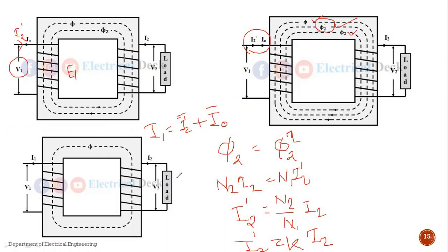And when the transformer is on no load condition, the current taken from the supply, that is I0, is again the vector sum of two components, that means the magnetizing component and the working component. The final conclusion is that the transformer operation remains the same whether it is operating on no load condition or on load condition. We have already concluded this in the previous lecture. Today I just had an overlook on that. याच्यावरती मी फक्त overlook केले.